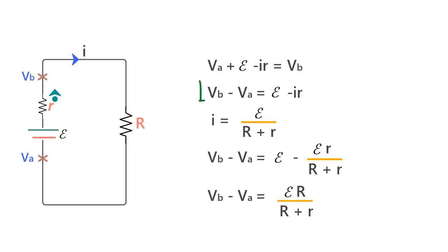So you see, to find the potential difference between any 2 points, start at one point and move in the circuit towards the other point and add all changes in potential algebraically. This would be the potential difference between the 2 points then.